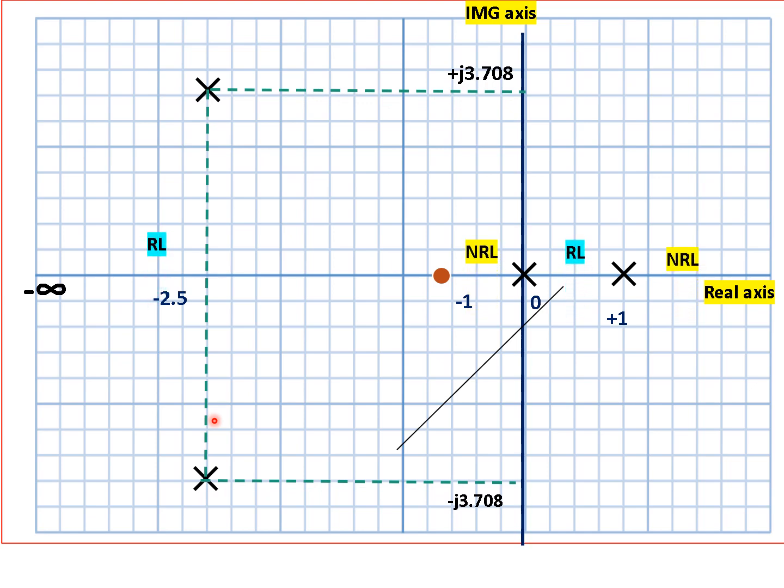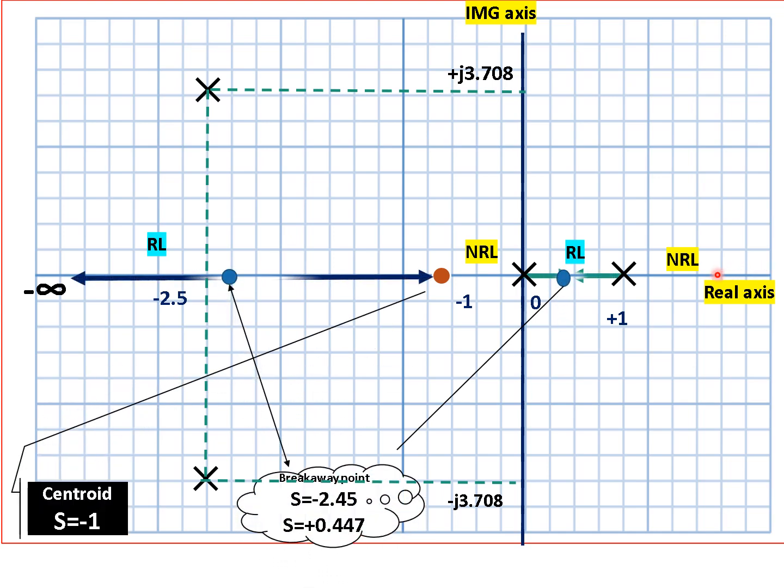So first we'll find the root locus existence. Now as we know, the root locus exists between plus 1 and 0, and the root locus exists from minus 1 to minus infinity. And no root locus exists between 0 and minus 1, and no root locus exists on the right side of the plane. So first we'll find the breakaway points.